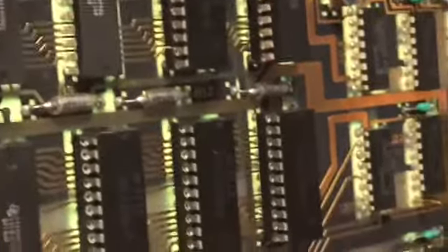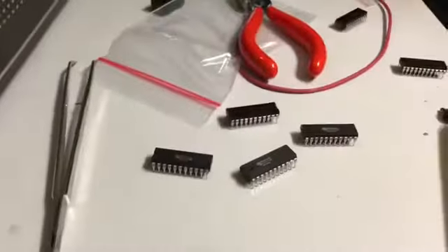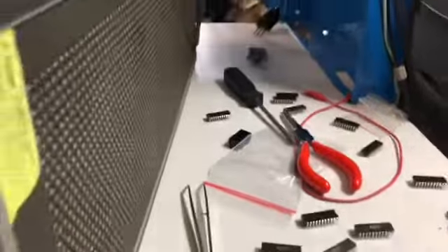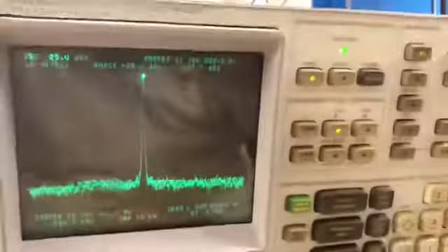and after all the refresh control has been replaced, it has been clear that RAM is the problem. I have swapped many times and many RAMs, since I don't have a way to test each single IC. But, well, it seems that we have some RAM that is not functioning at all.